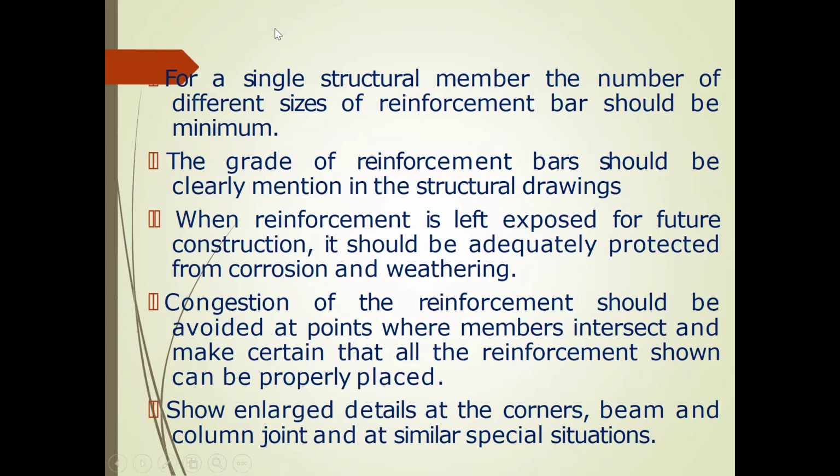For a structural member, the number of different sizes of reinforcement bars should be a minimum. The grade of the reinforcement should be clearly mentioned in the structural drawing. When reinforcement is left exposed for future construction, it should be adequately protected from corrosion and weathering.